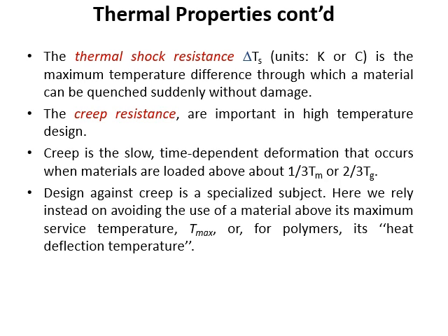For example, if you rapidly quench a metal from 200 degrees to room temperature 25 degrees, you don't have much difference, because the metal has a considerably high melting point and the properties, for example the mechanical strength, do not change. Of course, when you do the thermal shock with glass, for example, you might break the glass.